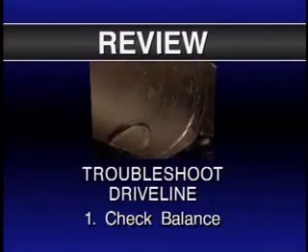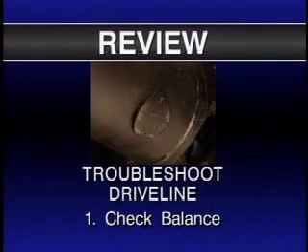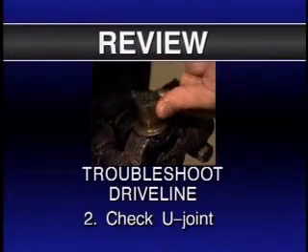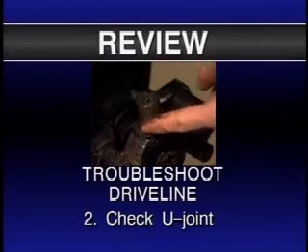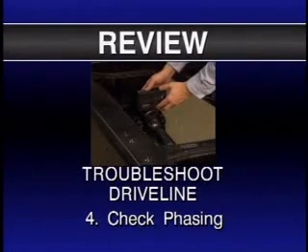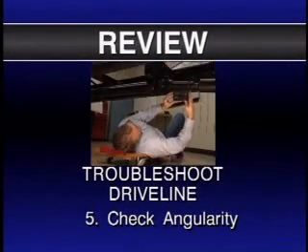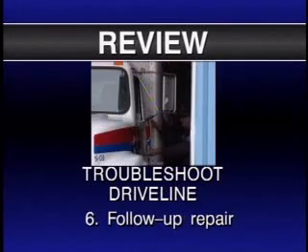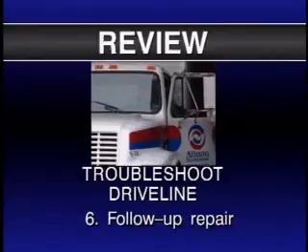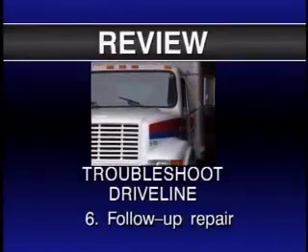If you think the cause of the vibration is in the driveline, begin troubleshooting with a check of the driveline balance. Then, inspect the components and U-joints and replace any that are damaged or worn. Check the runout, the U-joint phasing, and finally, the angularity. And don't forget to follow up repairs to make certain the vibration problem has been solved.